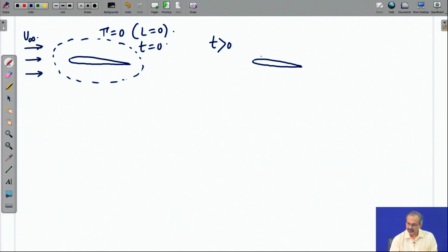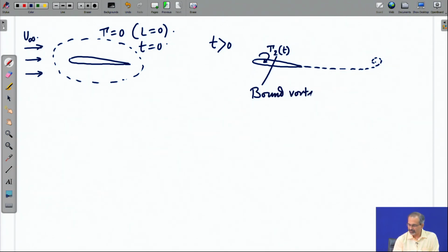came up on the airfoil, and instead of distributing the vorticity all over, let us say that we mark a single vortex associated with a circulation gamma 2, which we will see very soon, because we want to mark gamma 1 elsewhere, which we call the bound vortex. So, instead of a distributed system of vortices along a vortex sheet, for example, we have it lumped at one point, which we call the bound vortex.